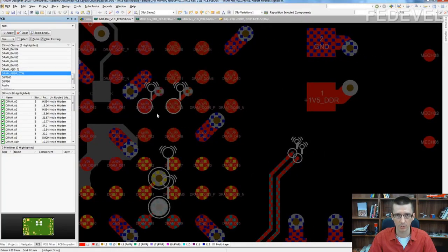Some engineers place micro vias on paths. I don't do that. In the past, we had problems with PCBs which had vias in path. We had problems during PCB manufacturing. We had problems during PCB assembly. That's one reason why I don't do it.